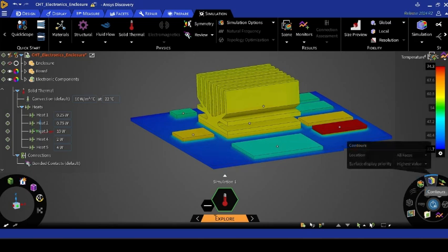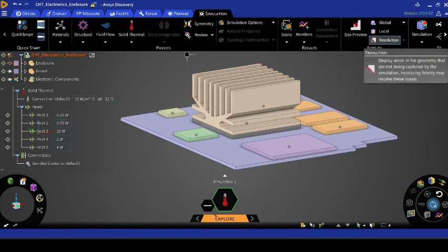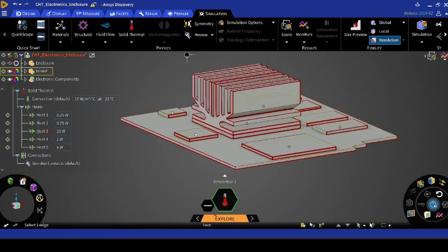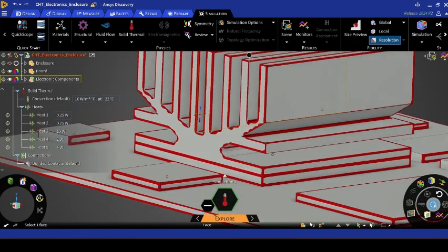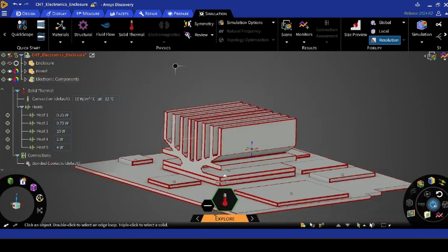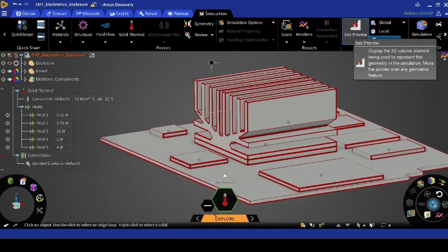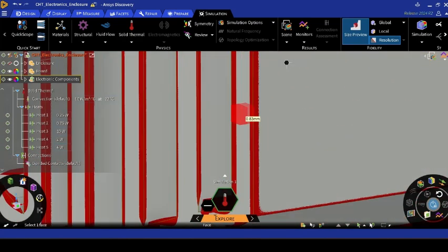Now coming on to the different things. Again, in here we haven't created any sort of a mesh, right? My results might not be that accurate, because it's explore mode in which we are exploring the design, so the results will not be that accurate. So I can see the resolution of the simulation that I am having, or the mesh. Basically it's called voxels that are being created in here. I might see that it's not that good, right? I can see the size of these voxels.